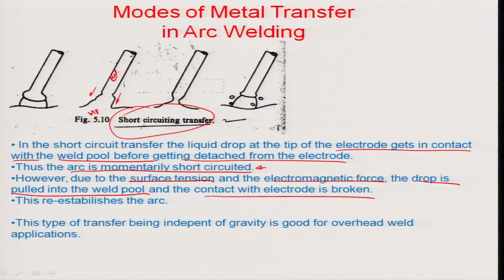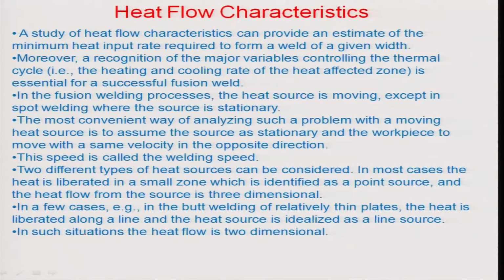So, ultimately any short circuited transfer process is followed up with a free flight, not a free flight exactly, but with a breakage of the connection which re-establishes the arc again, and then it can melt more material from the electrode in this process. So, this type of transfer, being independent of gravity, is good for overhead weld applications, you can say, and also, as I told you, the repelled case as well has good application to overhead welding applications.